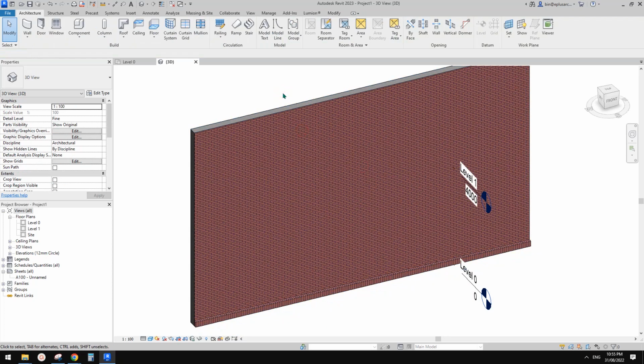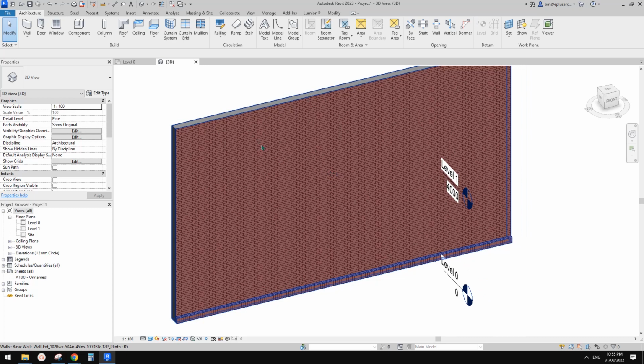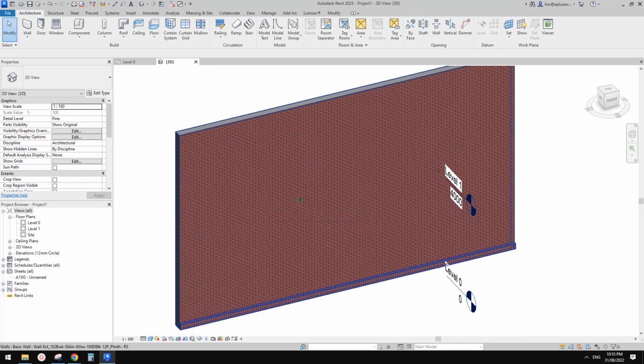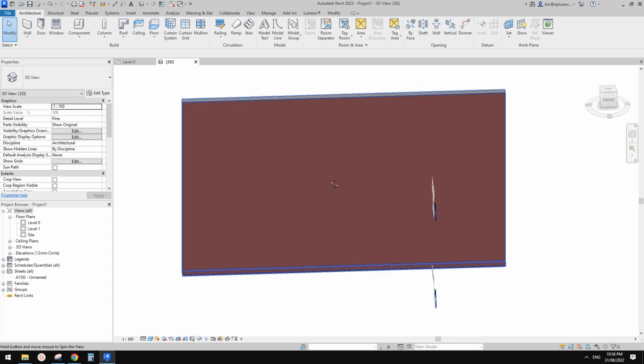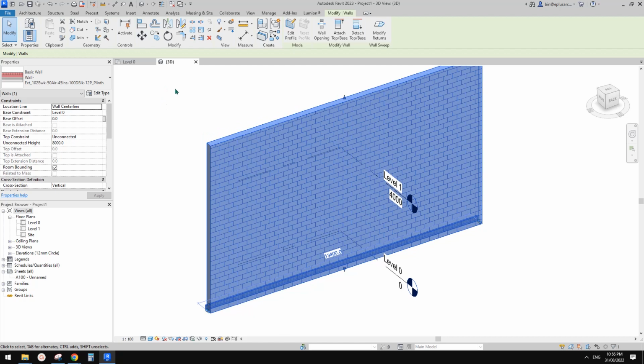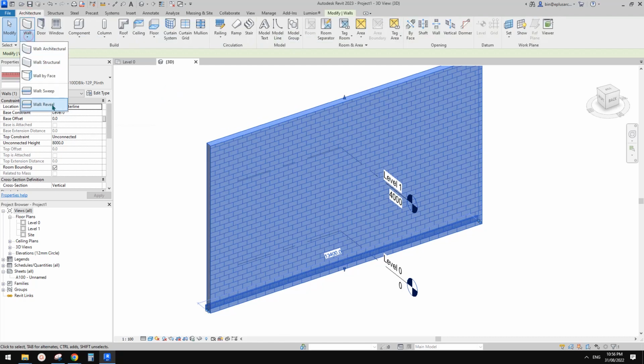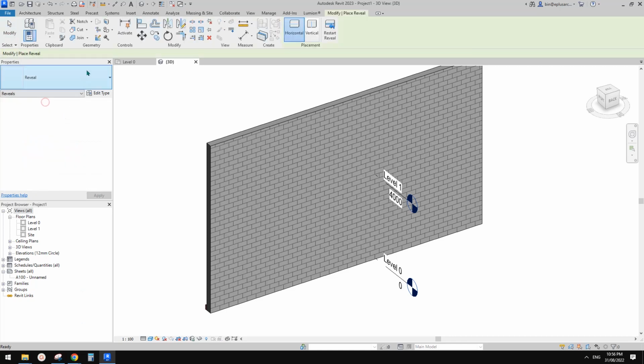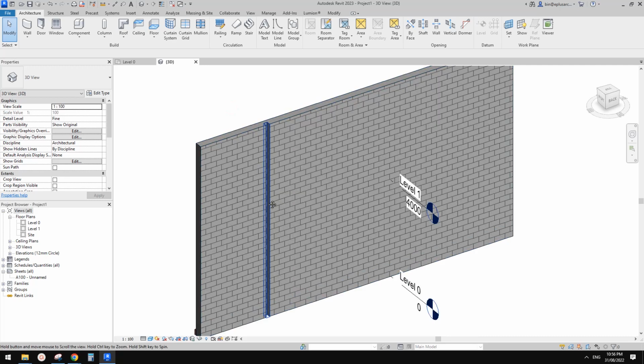basic one. And however, if you have some not very complex pattern, you can use the wall's reveal. Sometimes that can be quite useful. So for example, let's pretend that this is some precast concrete, and then sometimes we can add a reveal. It looks like there's no profile, so by default this is a big reveal. So of course it's not